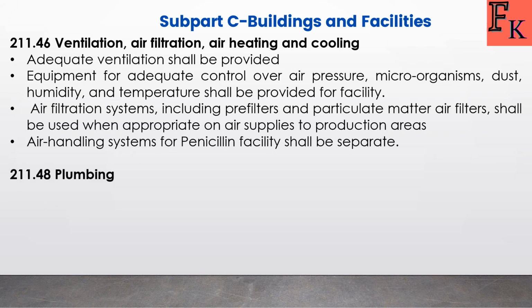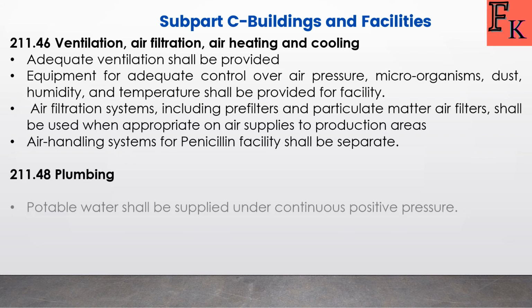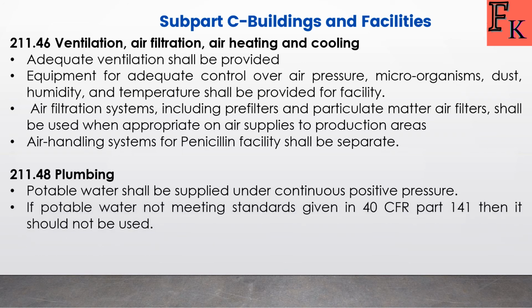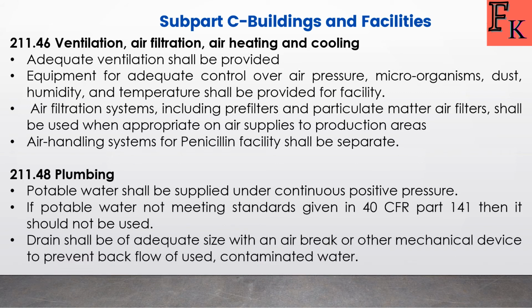Next section is 211.48 related to the plumbing. Potable water shall be supplied under continuous positive pressure. If potable water is not meeting standards given in 40 CFR Part 141, then it should not be used. Drain shall be of adequate size with an air brake or other mechanical device to prevent backflow of used contaminated water.